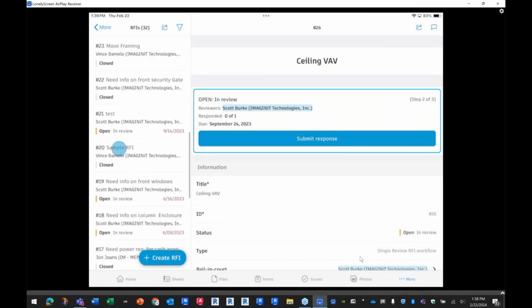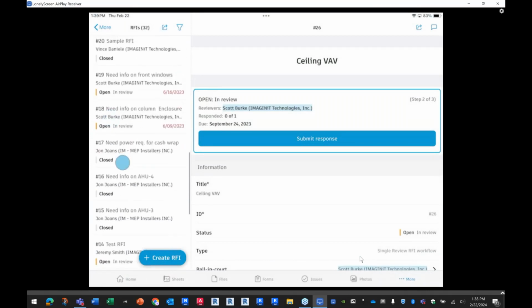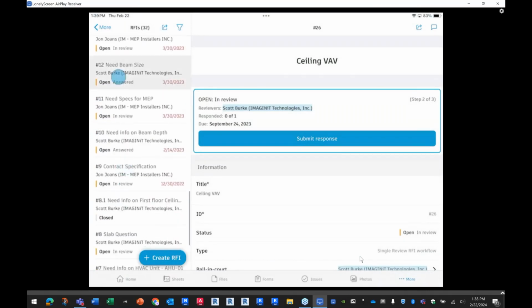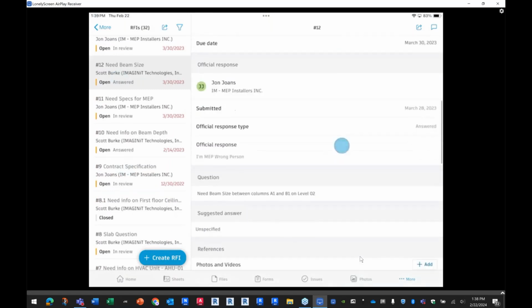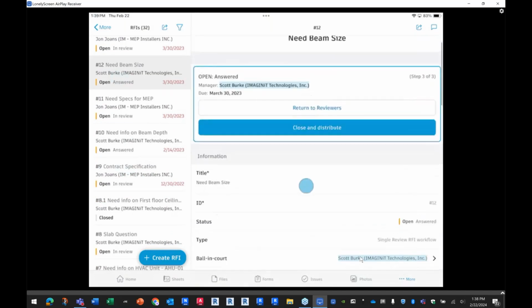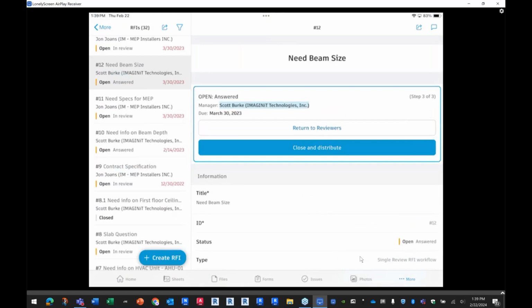So these are all RFIs in the various different stages right here. This one has been answered, so now it's waiting for the manager, who is me. I can see what the responses were. Here's the official response. It was answered, and so on. And I can close and distribute that RFI or return it to the reviewer, right? So I can actually do the full RFI process right here.